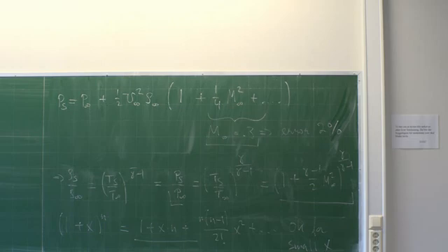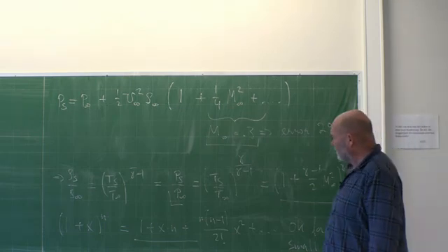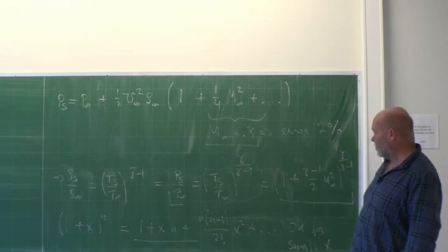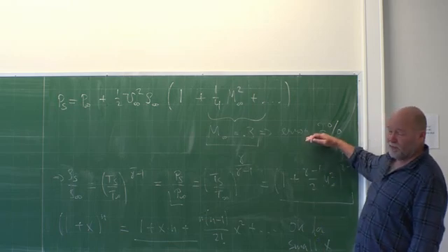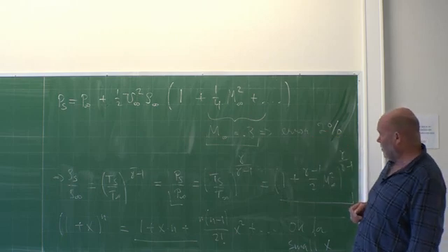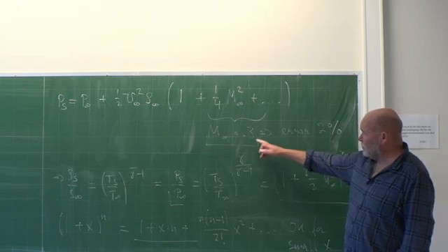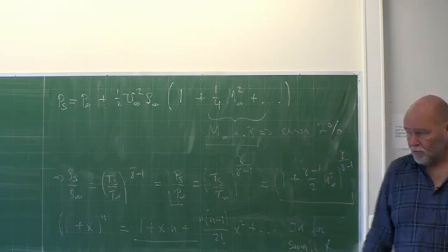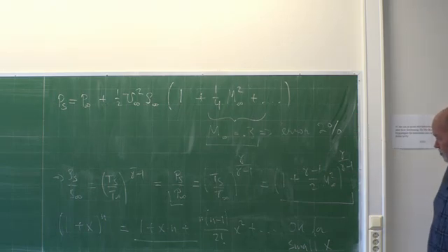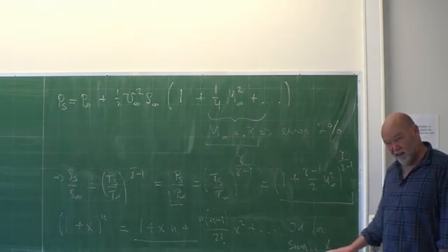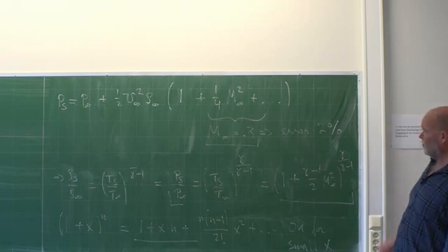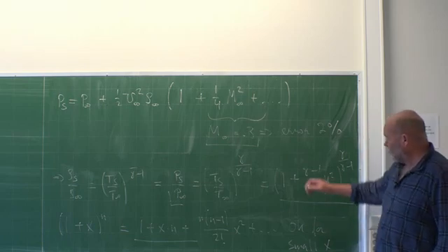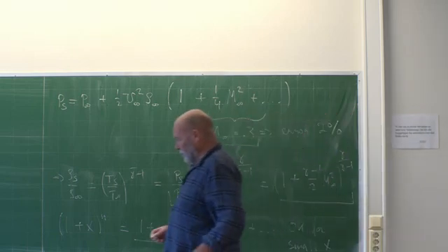When you don't have a velocity in your flow more than 30% of the speed of sound, then you can neglect the compressible effects altogether, because the effect is definitely very, very small indeed. But bigger than 0.3, then this one quite rapidly starts to grow, and then the entire theory here breaks down. Then the x is not small anymore. So then we have to do something a little bit more tricky. But I just wanted to show you where this 0.3 came from.